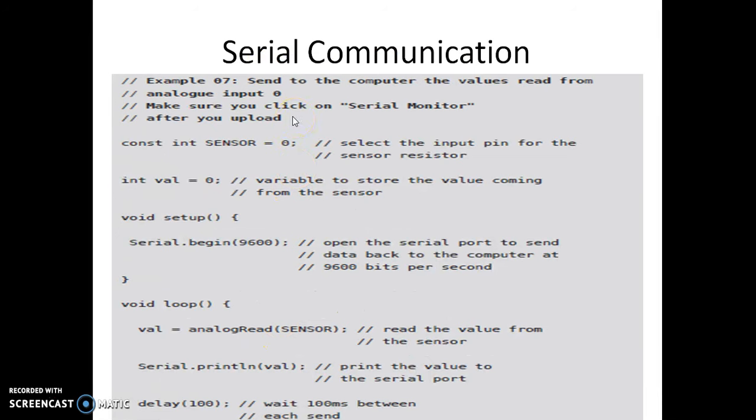Using the Arduino board, we can also do serial communication. This is one such program where we send to the computer the value read from analog input 0. Make sure that you click on the serial monitor after you upload this program. Then we can open the serial monitor and see the value that is